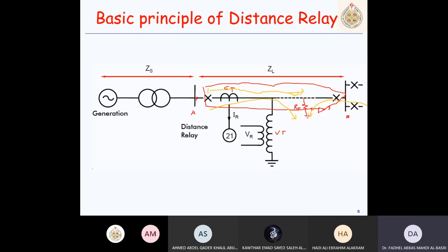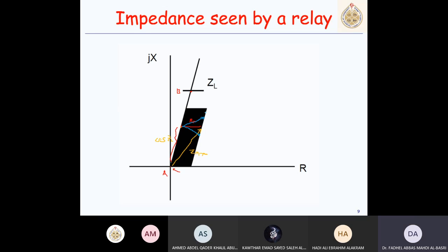So the relay will see this not as a resistance; it will see it as inductance plus resistance. So it is something like R plus this Y axis. As a result, the fault impedance, or this measured impedance, can drift from here. So we cannot have a straight line setting which is equal to just a magnitude. This is how the relay will see the fault impedance, the measured impedance.